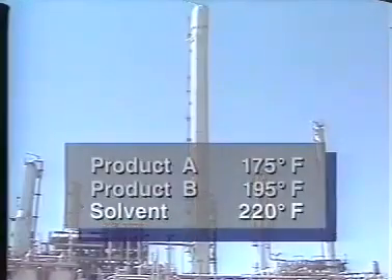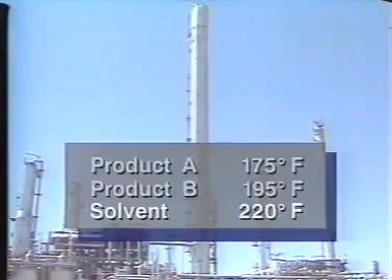The solvent used in extractive distillation has a boiling point that is considerably higher than either of the components being separated. Since it is heavier than both products, it falls to the bottom of the extractive column without being vaporized. The wide boiling point difference between the solvent and the component it absorbs allows us to separate this mixture by